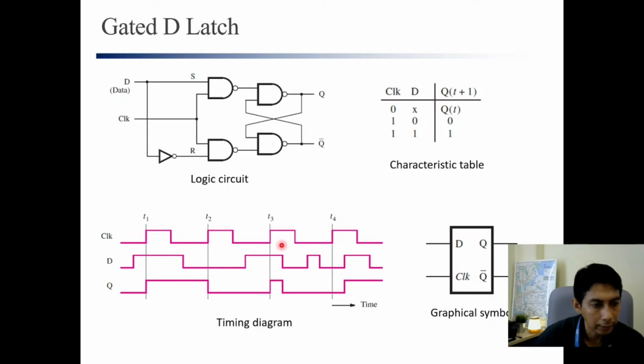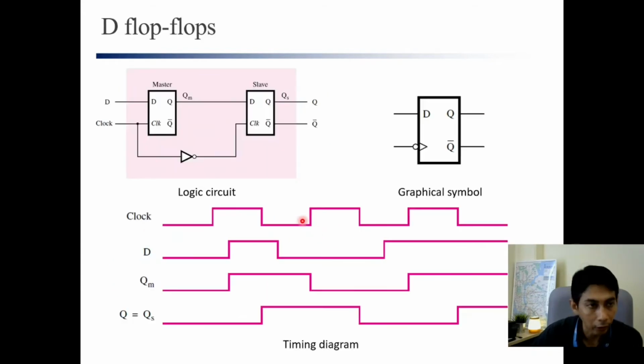And let's see here, when clock is active, here, this one is a better example. When clock is active, now the input, or D, goes to 1, so this will immediately follow. But for flip-flops, the sensitivity is at the edge of the clock only. For example, if we have a negative edge like this, the output, or the signal Q, will be sensitive to the clock edge.